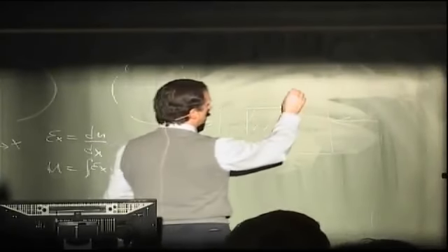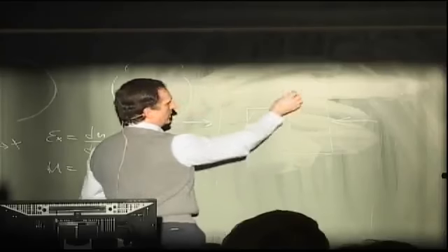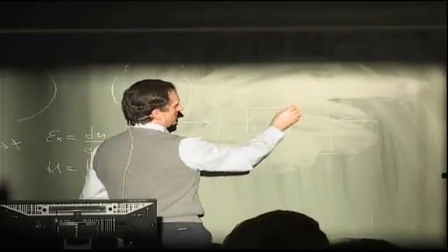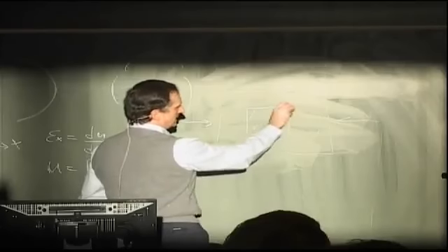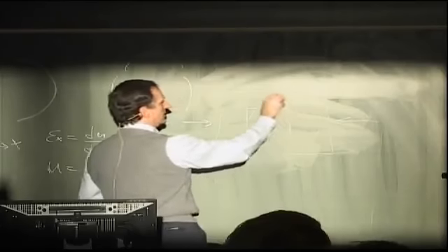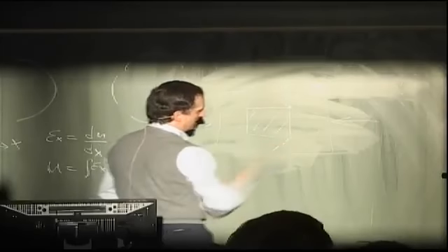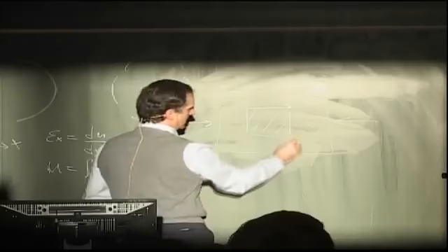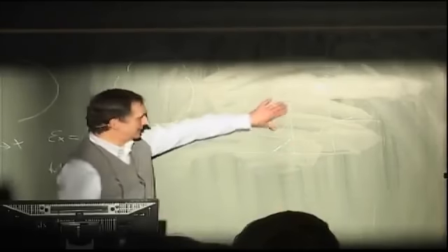In this case, all the displacement will happen around here. So a point on this line before loading would pretty much move. This point will stay in this location because it's attached here, and this is very stiff. So it would actually deform like this, and similarly, probably something like this on the other end for this originally straight line. That part is very difficult to capture with a simple function using a few terms. If I only use sine of pi x over a, one half wave, it would look like this, and it has very little capability of capturing this weird shape of the displacements over there. So that's why you need quite a few terms.